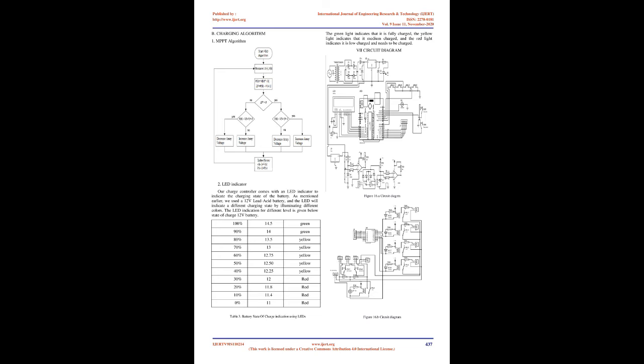2. Bulk charge, 2nd stage, from T1 to T2. After the battery voltage reaches the value VTC, a constant current I bulk should be applied to the battery. The I bulk is the maximum charge current that the battery supports without a big water loss, and its value is specified by the manufacturers. This current is applied until the battery voltage reaches the maximum value of overcharge voltage, defined by VOC, and also specified by the manufacturers.